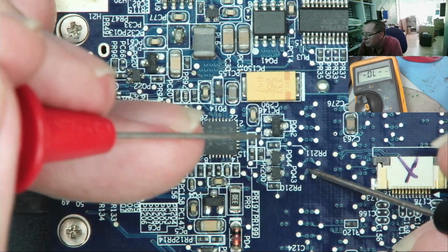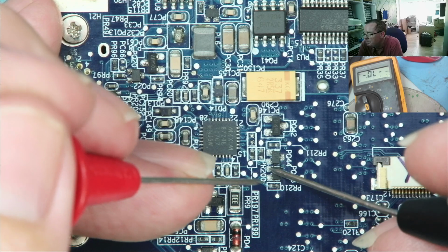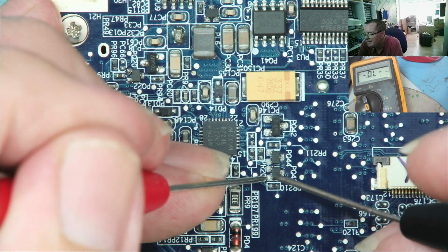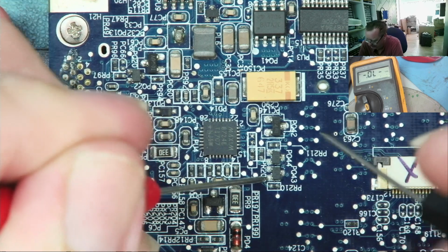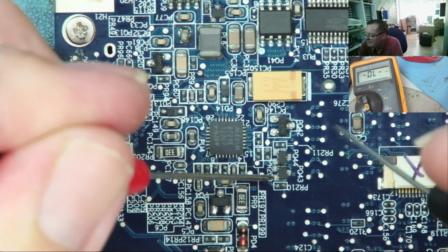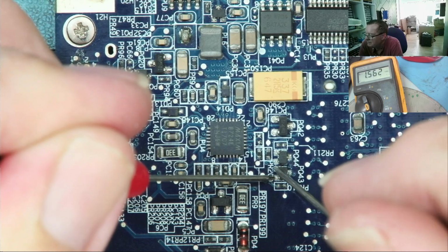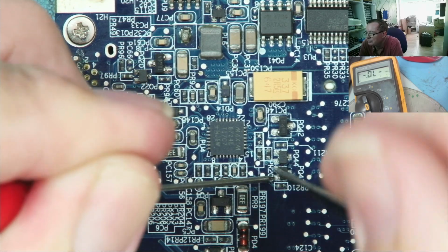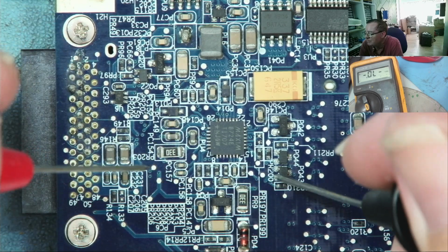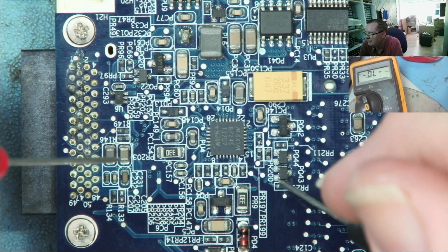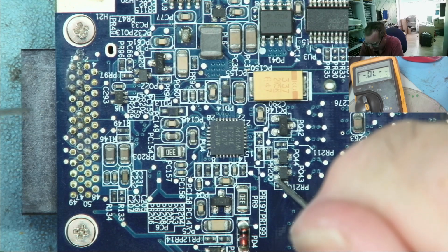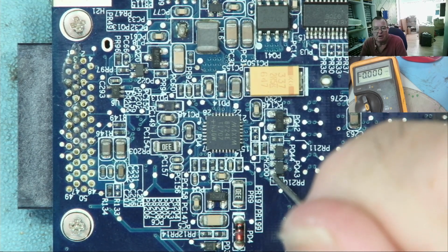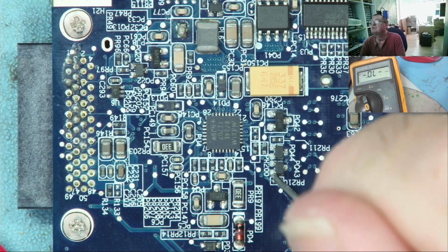And we'll probably also find, if this is the gate or the base, and this is probably going to be a gate because this looks like a MOSFET, if I put the red lead here, positive, to there, I see the diode junction. And I suspect this is probably the source. That's just a suspicion. But I can go a bit more than suspicion, and I'll show you what I can do.